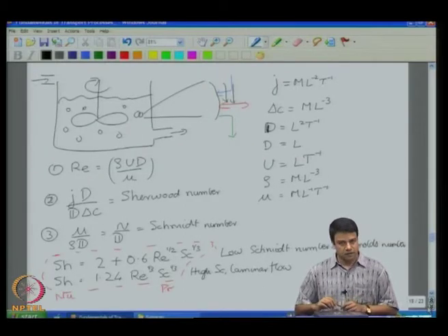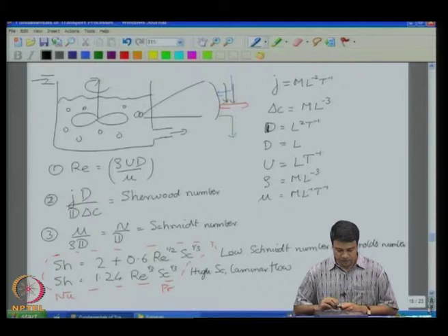And then we looked at the heat transfer and mass transfer from the surface of a catalyst particle. And there I told you the fundamental numbers: the non-dimensional mass flux, a Sherwood number, a ratio of a mechanical quantity, viscosity, and a mass transport quantity, the diffusion coefficient, and the Reynolds number, basically because the fluid flow is what is transporting mass to the surface. And we looked at two different correlations, for laminar flow and for high and low Schmidt numbers.